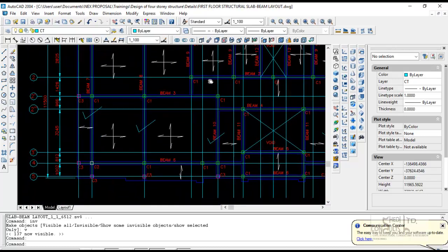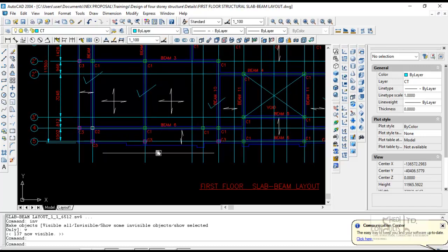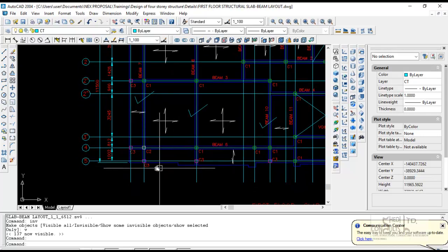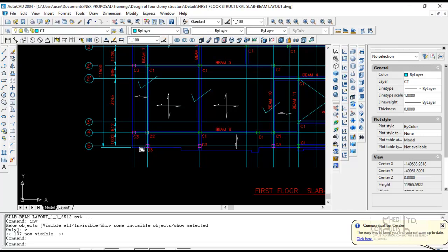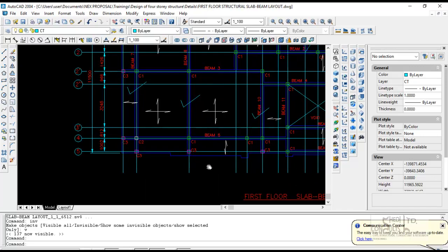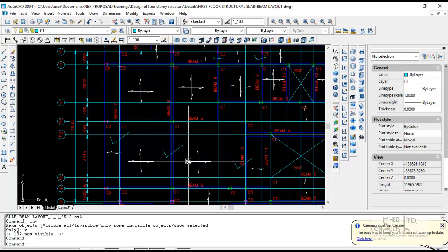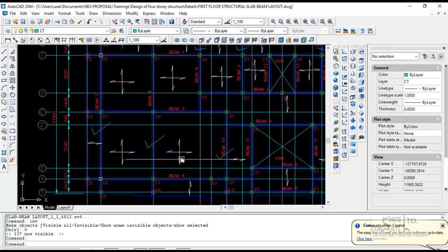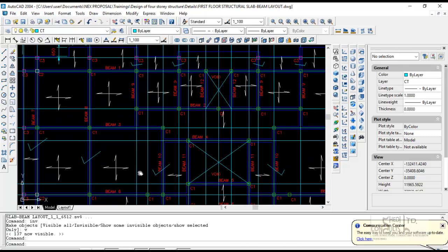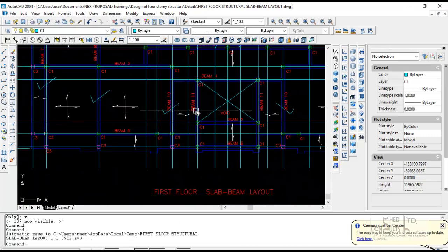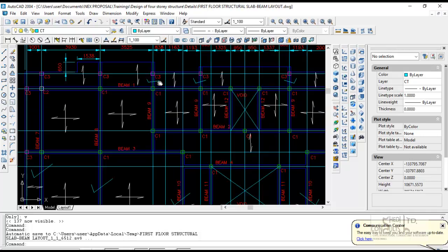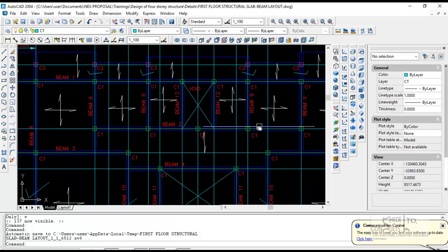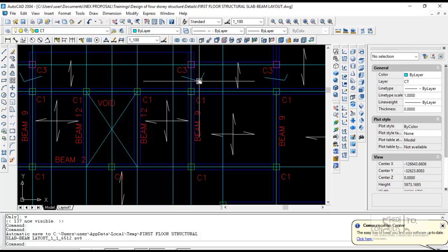However, the beams that have been ticked due to the cantilevers and the fact that they are carrying columns from the first floor upwards and they are going to be supporting the preceding floors, we are going to make those beams, the beams that have been ticked, 230 by 550. So these beams that have been ticked by using cyan are beams supporting the columns on the preceding floor. We are going to make them 230 by 550 beams.